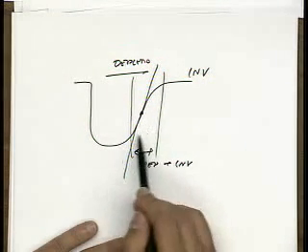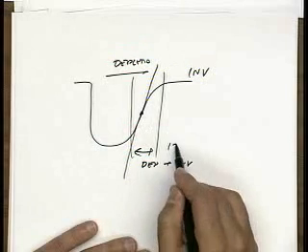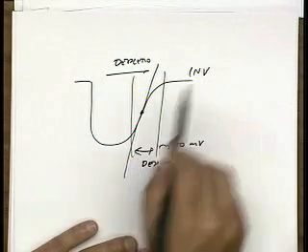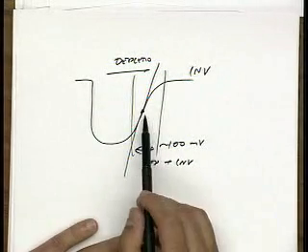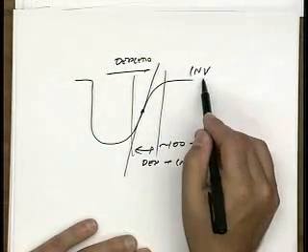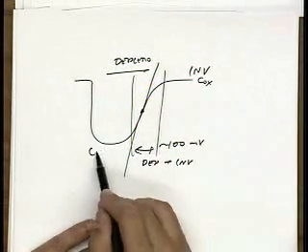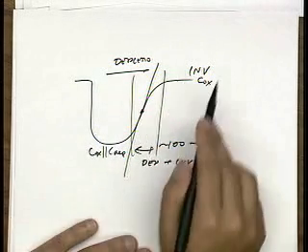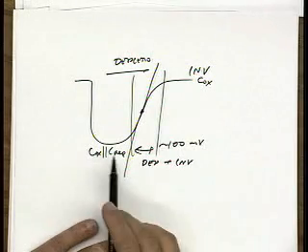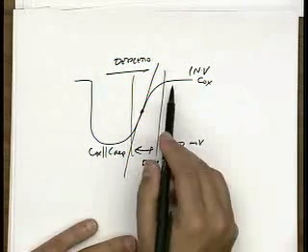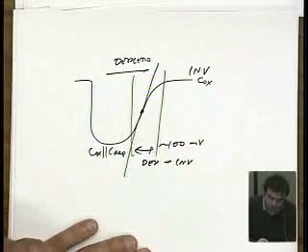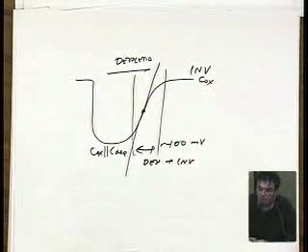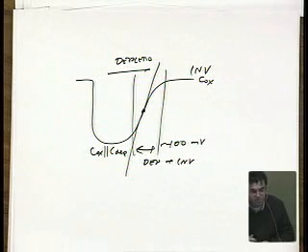And so right, within a couple hundred millivolts around VT, we see this transition occurring. And that means our capacitance varies from Cox to Cox in series with C depletion. And so this could be a 3-to-1 variation, 4-to-1 variation very easily. That means this is very steep. So our voltage coefficient is very bad.